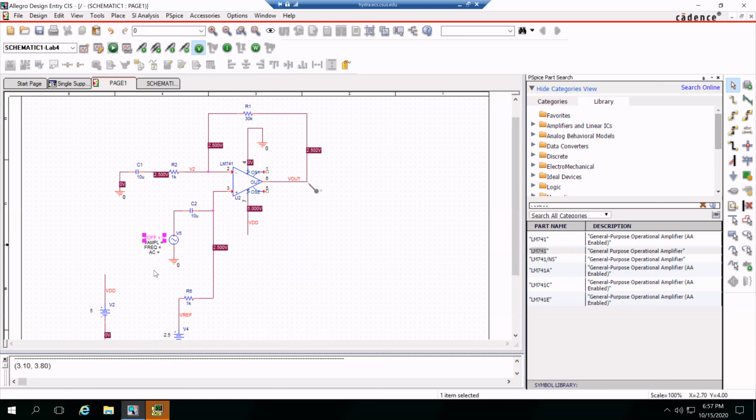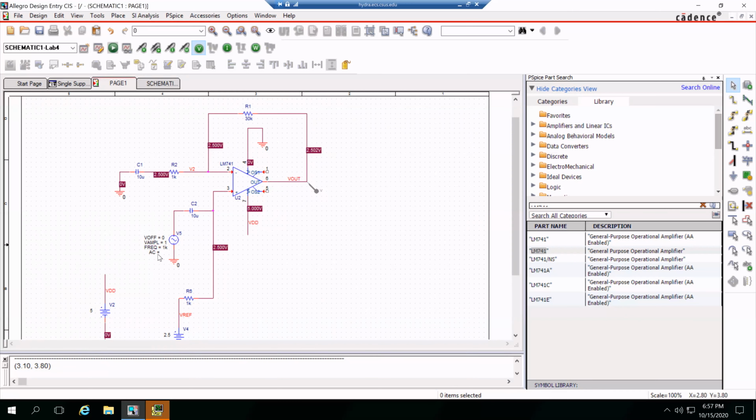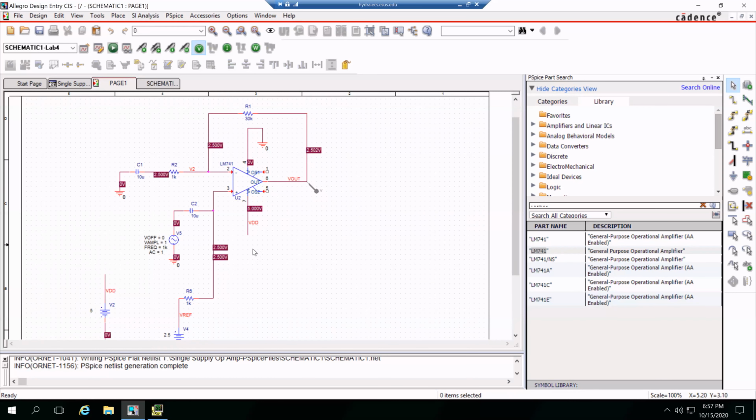0. And that doesn't really matter, right? Because we have a capacitor here. So you have DC decoupling, right? So even if you had an offset on this one, it would have no impact over here because you're through DC, you're forcing this to be at 2.5 volts. Let's see, AC1. Okay. So now we got everything hooked back up. We'll do one more DC bias point, make sure it's still good.